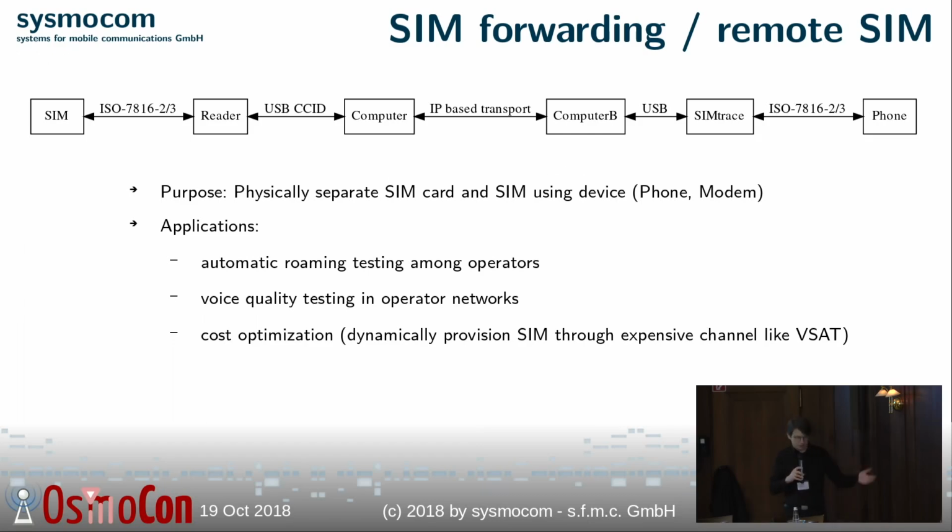I mean, what do you have? You have a SIM card implementing an electrical interface according to ISO 7816-2 and -3. You have a card reader of some sort. Typically, that card reader will implement a USB CCID profile. That's a standard USB profile that's implemented by almost all card readers today that attaches to some computer. And then on the other end, you have another computer, which then has the SimTrace 2, in this case, attached. And then you have this flexible printed circuit that looks like a SIM card in mechanical form factor